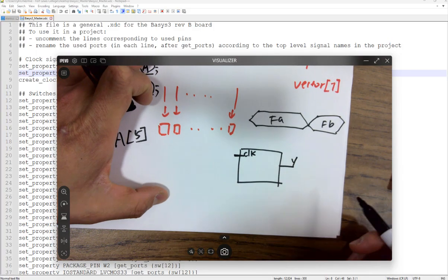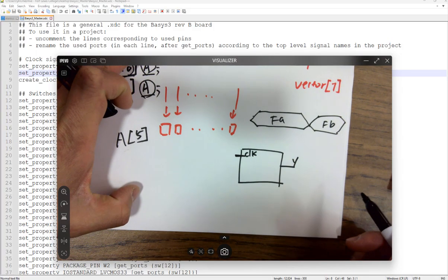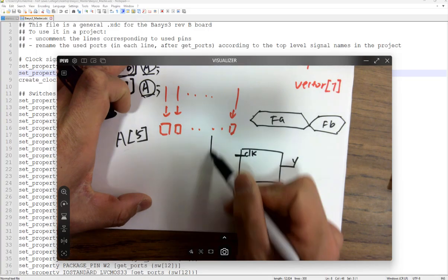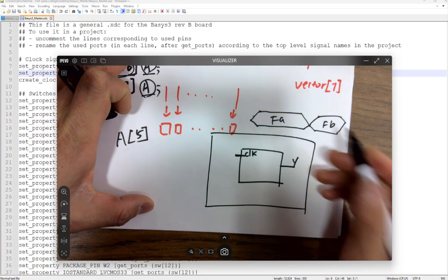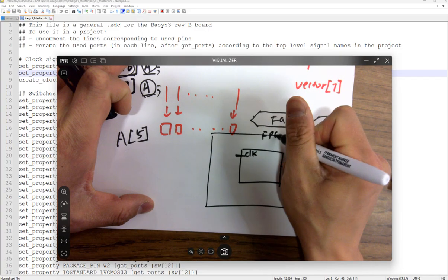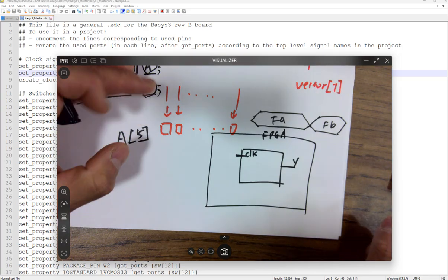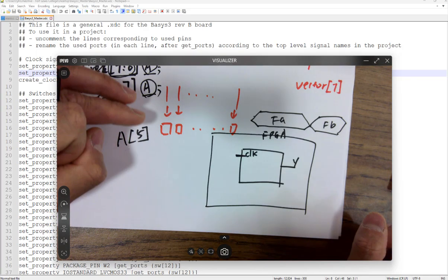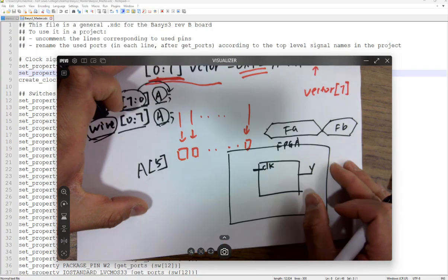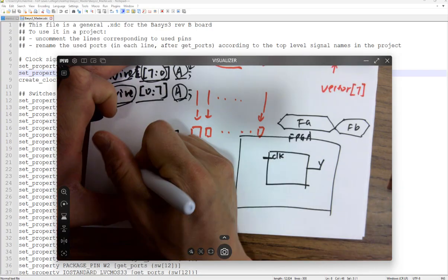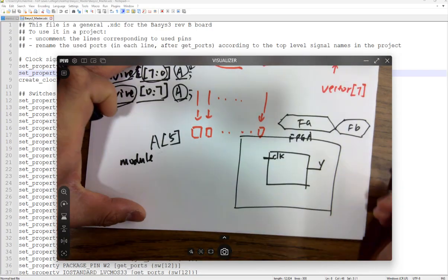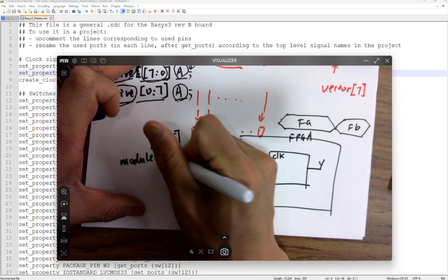And we are writing a top module, and the top is the FPGA top. Inside of the simulation you have been doing, keep in mind, the FPGA now is the top. Before it was your simulation software top, now it's a hardware FPGA top. So when you are writing a top, you still have to start with the module, and you just name it top, for example.